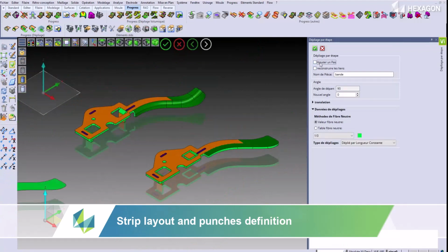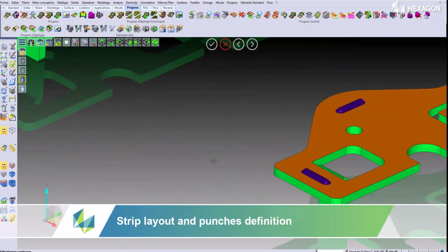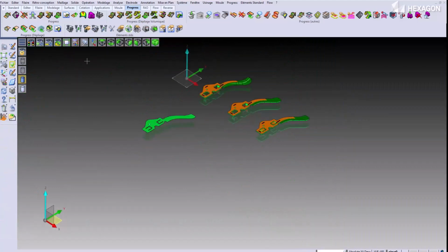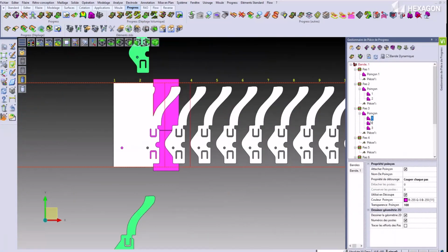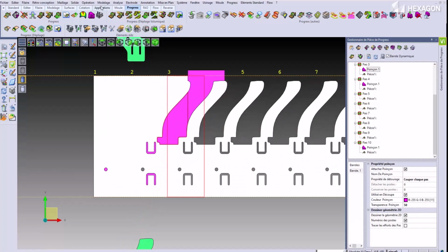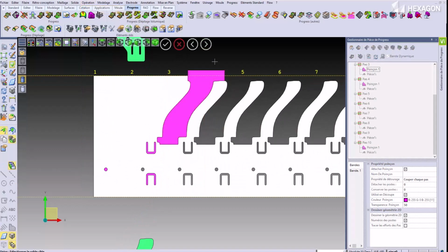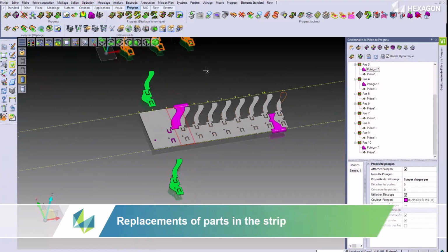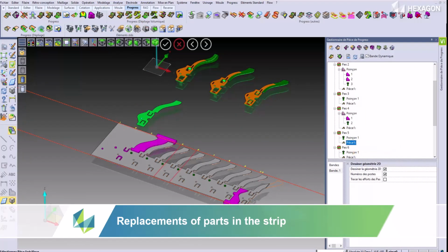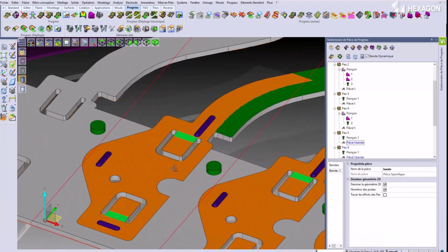Next, stamping operations such as forming, drawing, bending, and piercing are planned, and operations are assigned to die stations. The resulting plan is called a strip layout, which guides the subsequent die structure design. Strip design is the most challenging task in progressive die design, and VISI helps guide die makers to engineer the proper sequence. A progressive die's productivity, accuracy, cost, and quality mainly depend on the strip layout and stamping process.